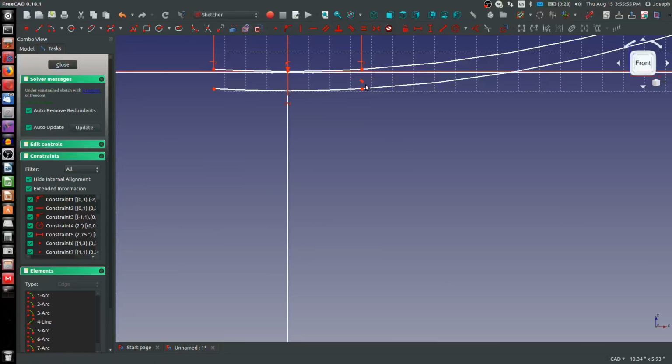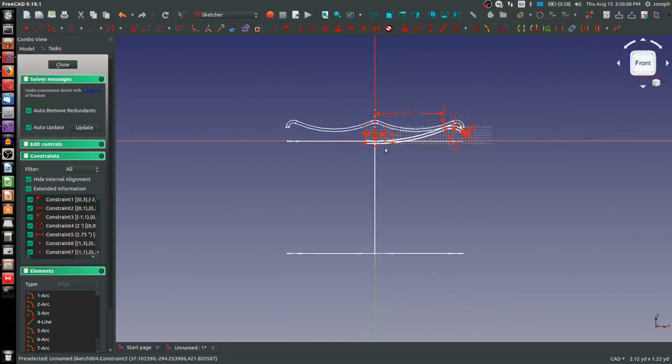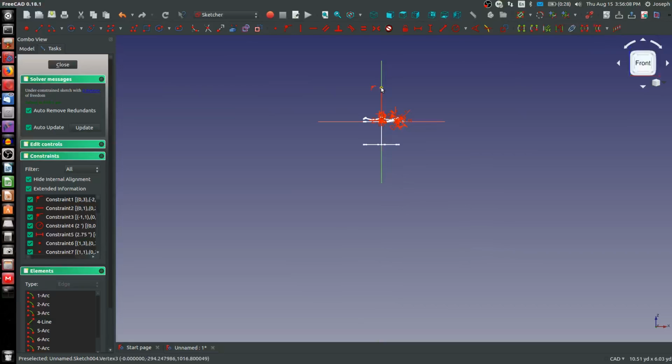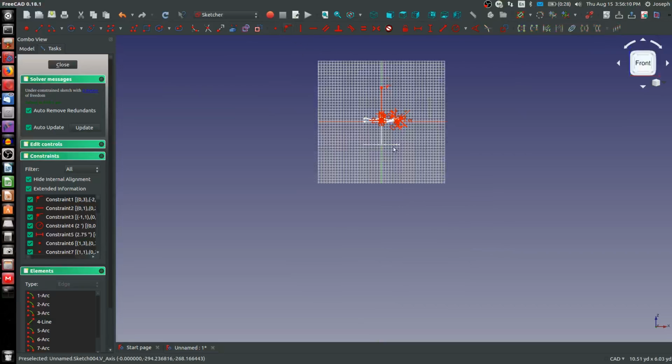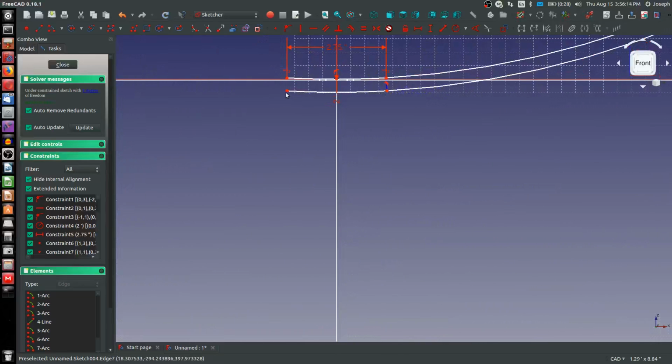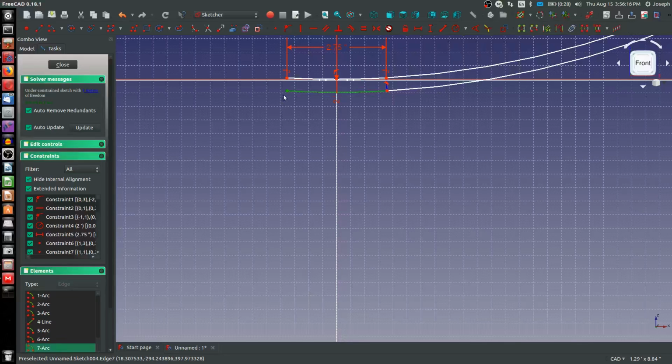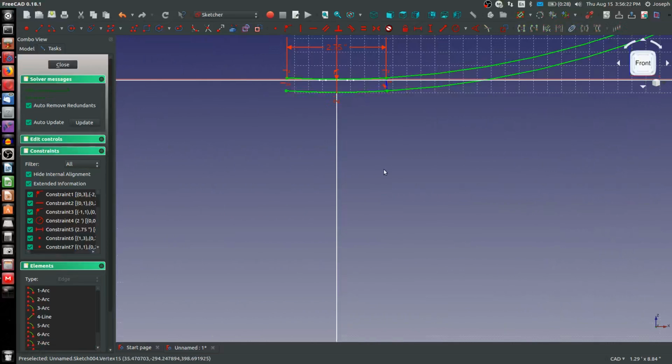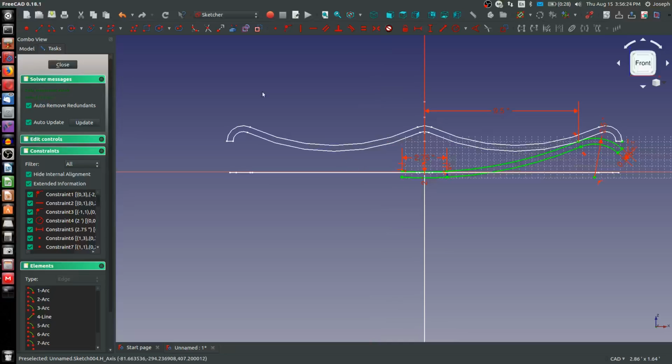So, how do I properly place this? I think the most dynamic way if something were to change in the sketch in the future is to draw a construction line from point to point and make it coincident to the center of that arc. Finally, we've got 1 degree of freedom, and it's because I need to add another relation, horizontal. There we have it.